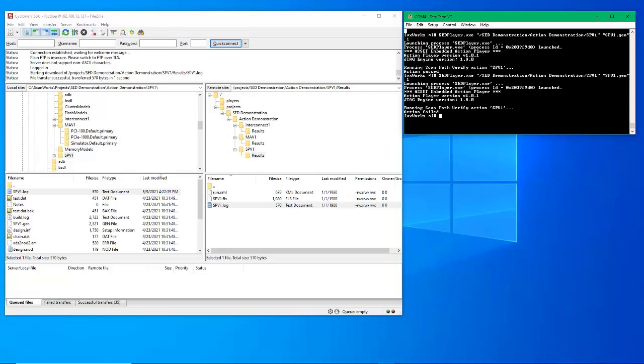All right, so for the interconnect test, before I do that, let me make sure I've got all my switches set, because we're going to create an interconnect fault. I believe the fault that we're going to create is a short between two I/O on the board. So let's go ahead and run that test. Again, I'm going to copy the command. I've got it in another window, so you don't have to sit here and watch me type that command. This is the command that will run the interconnect action.